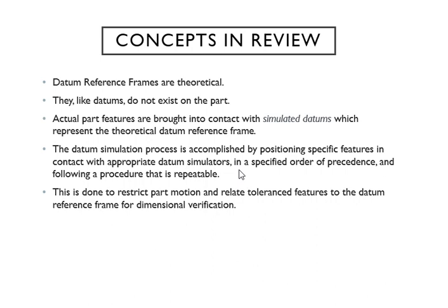Review again. In the datum simulation process, we put the datum simulator with the datum feature, and then you specify the order. The precedence depends on the functional design, and of course that's a repeatable procedure. Again, what we do all that for is dimensional verification, because it's important that your manufactured part is exactly as accurate as you have drawn.